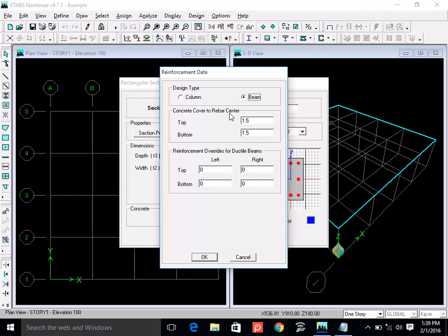One thing is called clear cover. Right? Clear cover is from the face of the concrete to the edge of the steel bar. Right? But we are talking here about the effective cover to the center of the rebar. Okay. What is generally the cover for beams? 40.